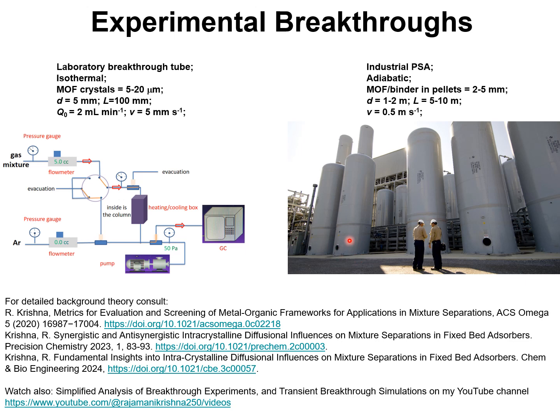The interstitial gas velocities are significantly higher than in laboratory scale units, say of the order of half a meter per second. The analysis of breakthrough experiments and translation of such breakthrough experiments to industrial scale PSA units is an important but not trivial task.